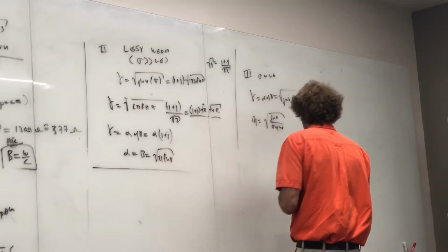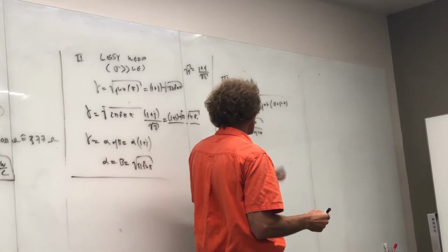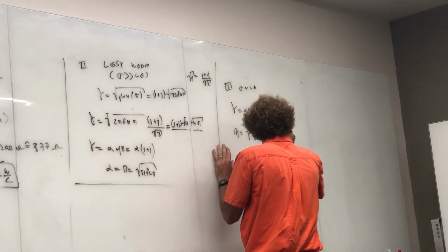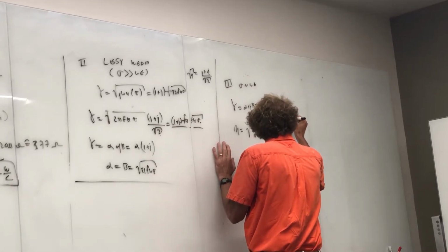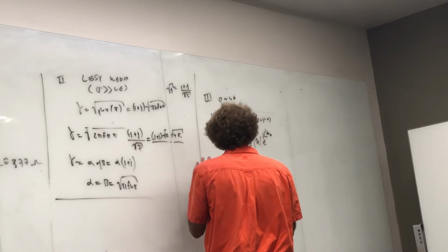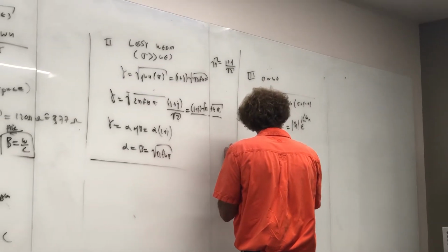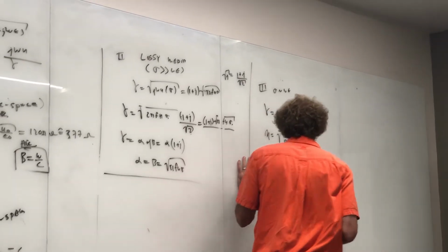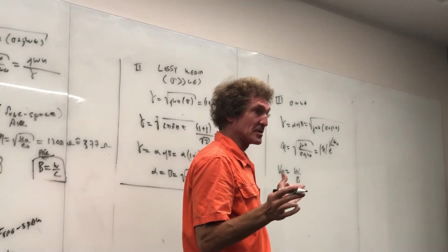Now you have to do that, and these are going to be complex numbers in general. This will have a magnitude and a phase angle. It's going to have some magnitude of eta, e to the j phase angle of the intrinsic impedance. The phase velocity in this case will be equal to omega over beta, but you have to calculate beta from this equation. So it's not a simple equation in general.